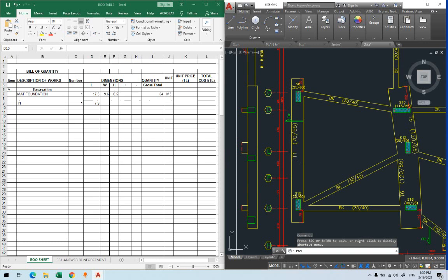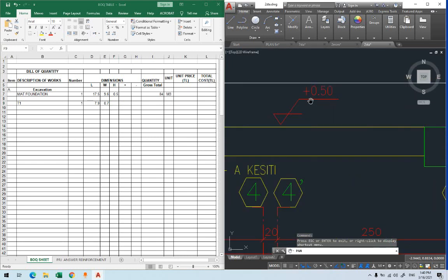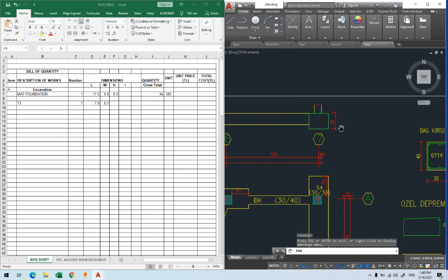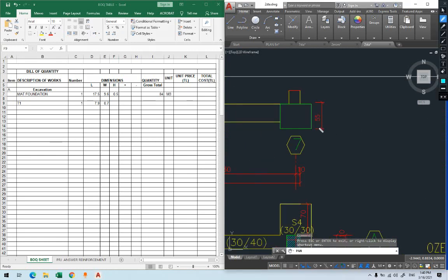I made a mistake: 1.7, 1.5, 2.35, that's it, 0.95, 0.7, 0.7. Then the width of it is 0.7, as we said here. This is 70 centimeter. Now, I'm not going to write 55 here, remember. The height, this is excavation. We need to see, this is plus 50, so the natural ground is somewhere here, which is 0, 0. Since the depth of the excavation is 55, we go 5 centimeter below the ground level.